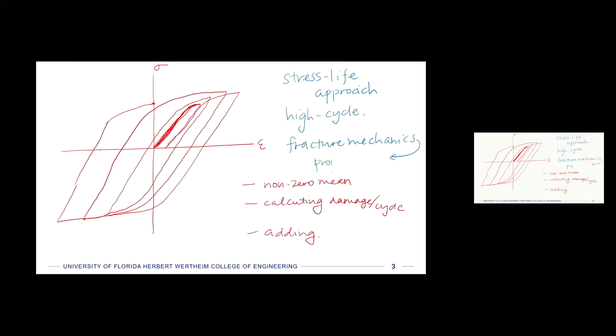And we're not just going to talk about propagation as either not propagating or propagating to failure, because that's kind of what we had before, in the extra lecture that I recorded last Friday. There was this fatigue or failure assessment diagram. Do we have ductile failure? Do we have brittle failure due to a crack? And you kind of just say, yes, a crack is going to propagate and the whole thing's going to collapse, or the crack is stable. But in real situations, there's actually stable crack growth in between there.